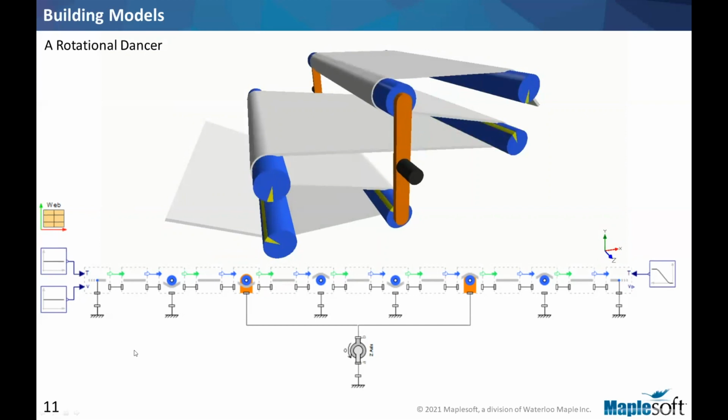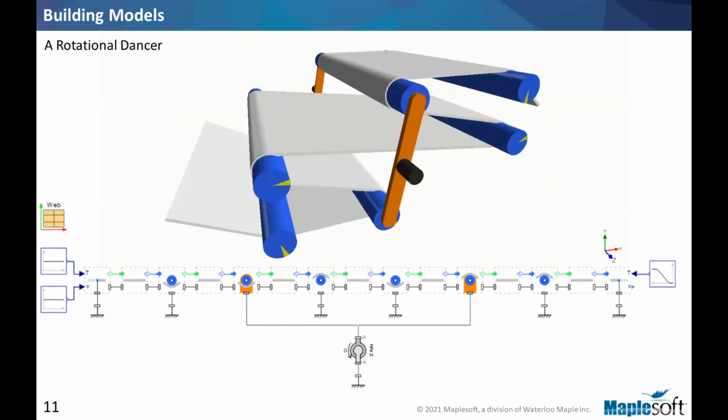approach, where we plan out the model, we place fixed rollers where we want to put them, and anything that moves, we come up with a way, is it a linkage, an arm, a slider. We use either the primitives inside the web handling library or the rest of the MapleSim libraries to make sure that we capture the motions and dynamics exactly as we want them.